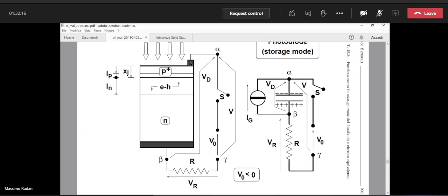You remember that when there is an excess of electrons and holes and they diffuse parallel to each other, they recombine. So the optical generations that occur in the neutral region on the upper part of the device are lost. They are absolutely of no use for the purpose of detecting the light. And there are many, because the exponential decay of the flux has just started, as we are near the surface.